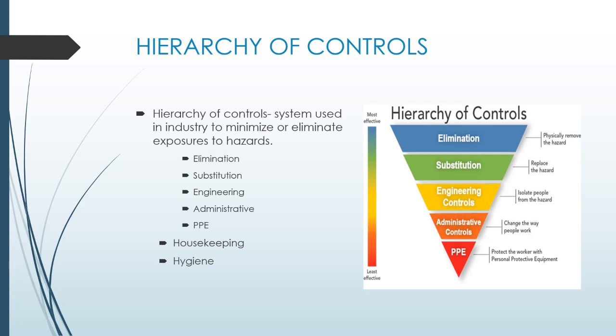I've added a few things to the hierarchy, and that's housekeeping and hygiene. Housekeeping is cleaning up after ourselves, minimizing that dust using wet sweeping methods and HEPA vacuums, and washing our hands before eating, going on break and eating a sandwich, things like that. Housekeeping and hygiene is our personal conduct of keeping the dust out of our lungs.